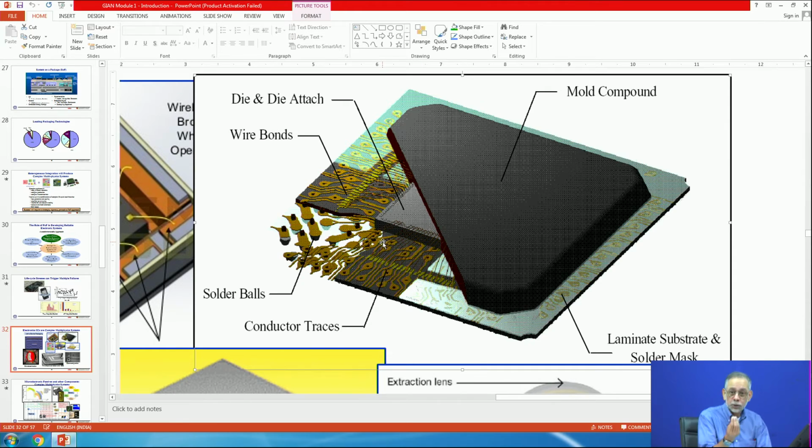It cannot cause corrosion on the rest of the IC because it's covered with a passivation layer, silicon nitride passivation. But the bond pads are exposed so you can make electrical contact, and that's metal, and there'll be corrosion over there. So A, it's corroding over time. B, you're keeping on pushing on it over time. Collectively, it eventually causes a failure. So that's what that picture was.